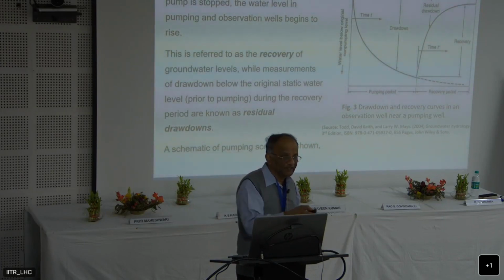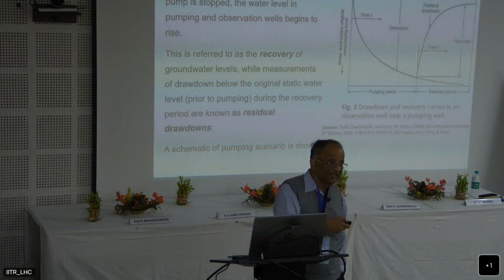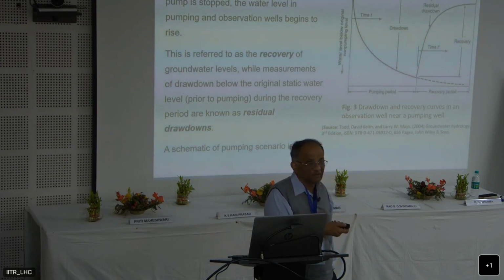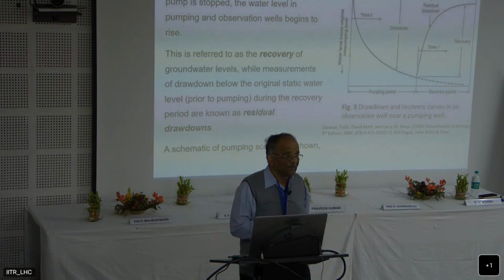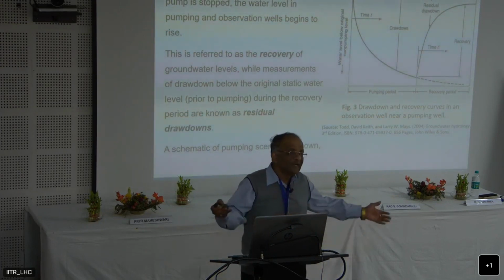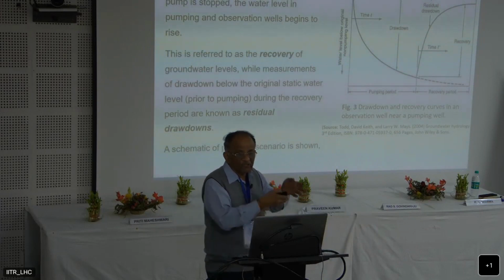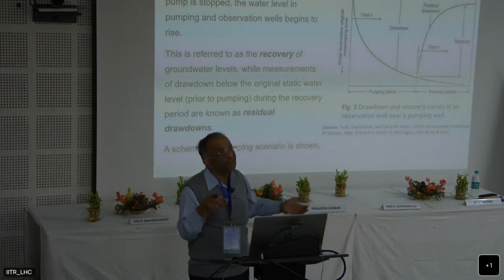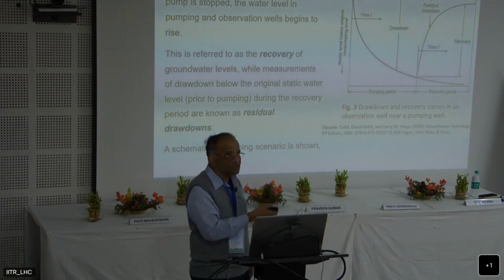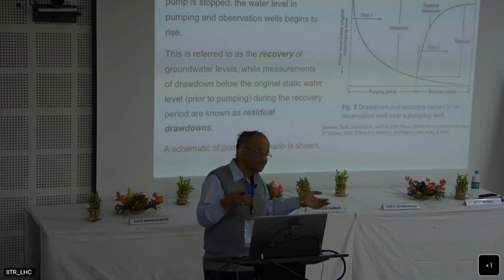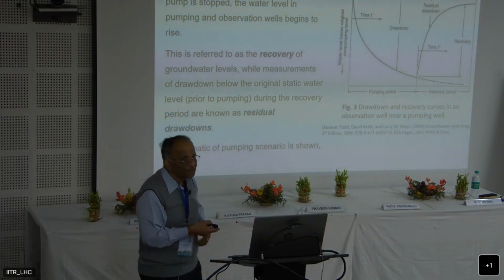Typically, it will recover in 4 to 5 hours, even though we have pumped for 3 hours, 3 days. If I allow it to stop, within 6 to 7 hours you will get back the full recovery. During the recovery stage, the entire aquifer is contributing. Whereas when we are pumping, the aquifer far away from the pumping well will not be contributing. That's why the drawdowns will be more as time goes on, but when you do the recovery, the affected aquifer portion will be contributing, so the recovery will be much faster.